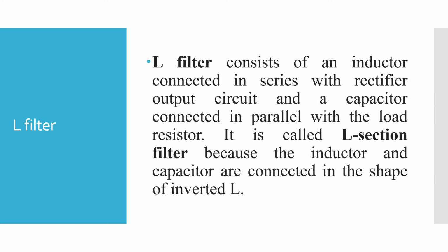The output DC voltage from the rectifier circuit passes through the inductor, or a choke coil. The inductor has low DC resistance and extremely high AC reactance. Thus, ripples get filtered through the choke coil. Some of the residual ripples, if present in the filtered signal from the inductor coil, will get bypassed through the capacitor. The reason behind this is that the capacitor allows AC and blocks DC.